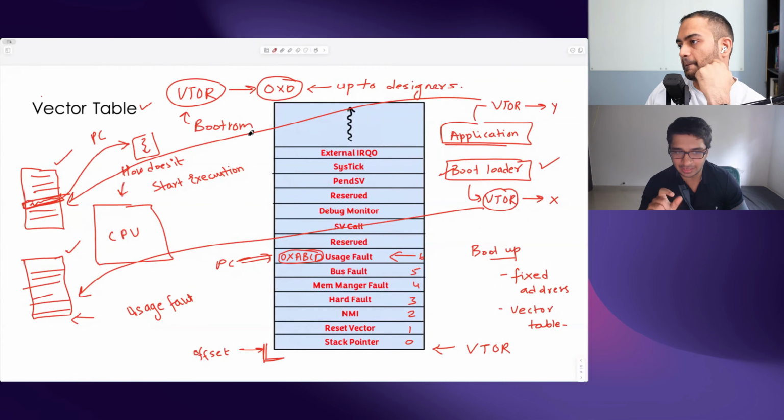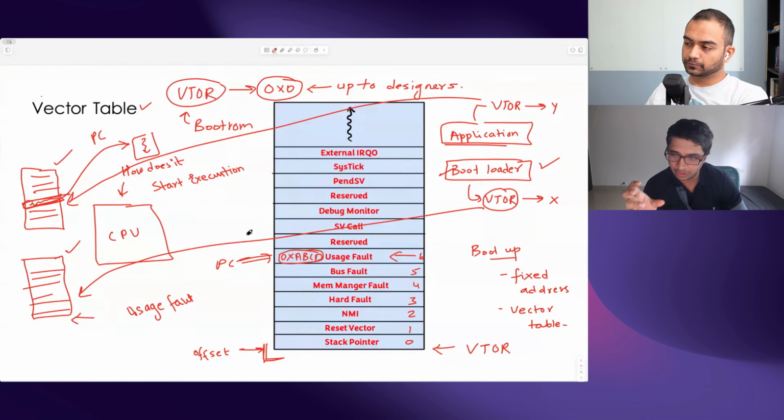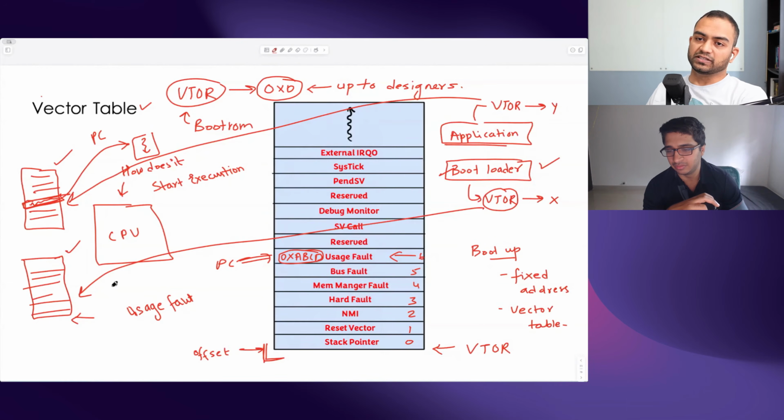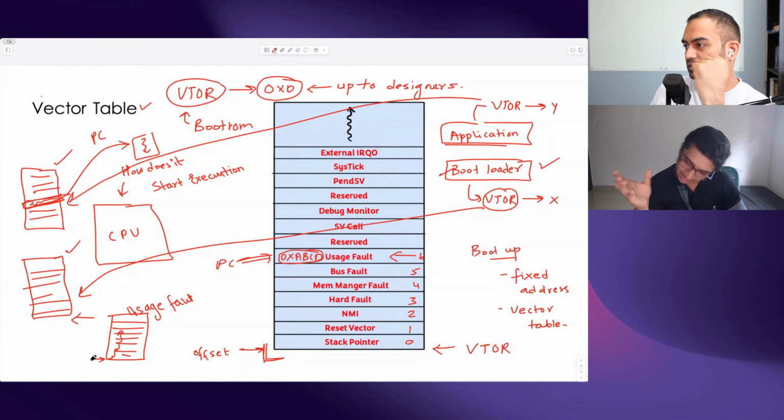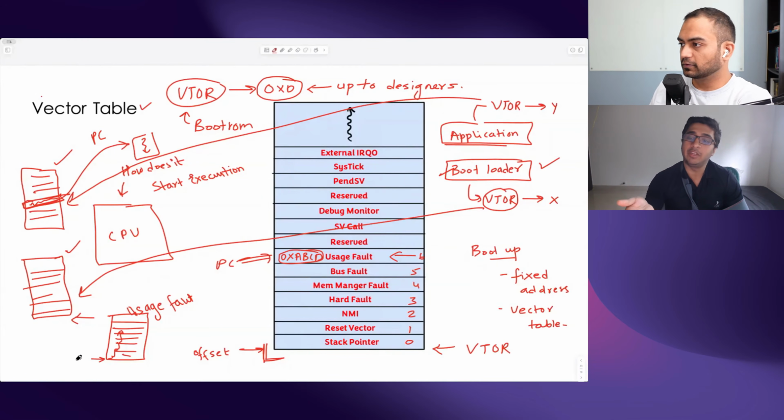And we will look at an example of it when we start working on our kit, and that the VTOR is not always zero. Usually you place the VTOR at the place where you want to start executing your code. So wherever your code sits, the VTOR would be pointing there. VTOR, vector table register, and you load the VTOR with the starting address of that memory. Correct. But we would not load it, essentially. The user won't. It's the responsibility of the previous firmware to make VTOR the correct value for the next firmware.